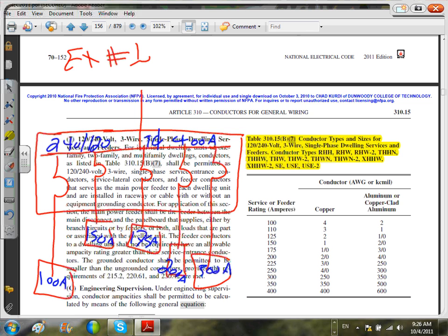How do you come up with these amps? We're going to do that in load calculation, guys. Why did I come up with 400 amp, not 1000 amp? That's called load calc, coming later. So suppose after your load calc you came up with these systems: residential, 240/120, dwelling. So what do I need from you guys? I need you now to size the conductors.